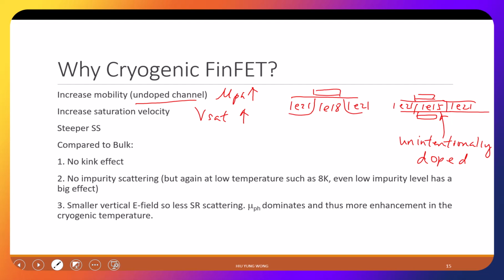More or less, here's why in that case the channel is low. And here I guess it's really about the magnitude, right? So there's some doping, but we just draw like a threshold, that it is too low just because of the background doping. You cannot get 100% pure silicon for low price. Okay, so this would be like other isotopes of that? No isotope. It can be impurity. But how can you have 1E23 atoms per cm cube? Now you're talking about within 1 billion silicon, I only have 1 dopant, right? I only have 1 impurity. It's very difficult to go to 1 trillion, right? Or quadrillion, right?